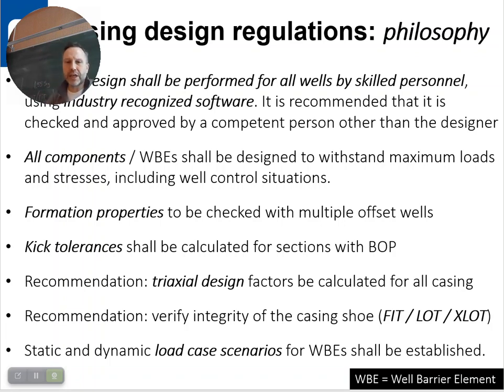Yeah. Triaxial designs, yes. FIT, leak-off tests and, yeah, load cases, static and dynamic. When you are producing the well, when the well is shut in, for example. Let's face it, the real extreme forces are during production, not during drilling. During drilling, you have some torque and drag and maybe a kick and so on, but unless you really do something bad,